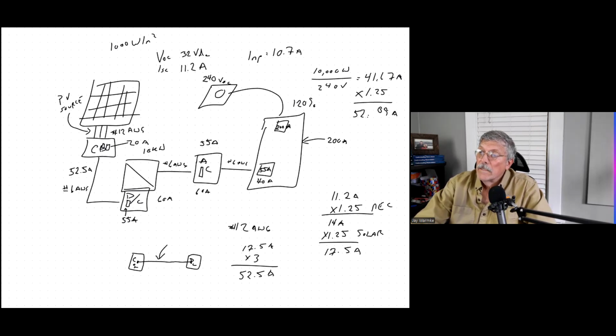Problem is, we're needing 55 amps. So we'd have to do several things here. We would have to either upgrade the box itself, maybe go to a 225 amp box, which would mean that I could go 25 plus 40, which would give me 65 amps. That would work.